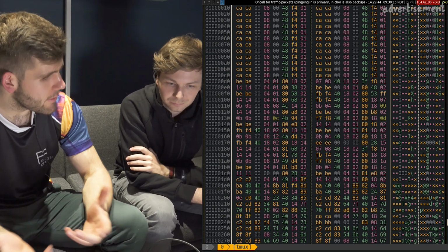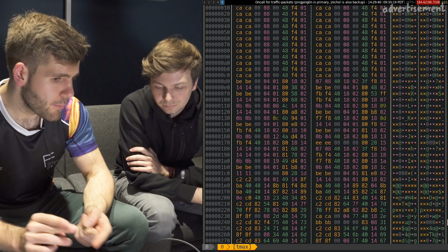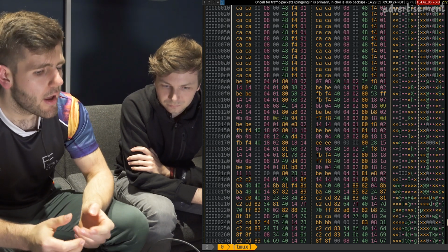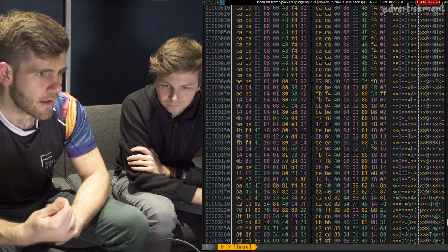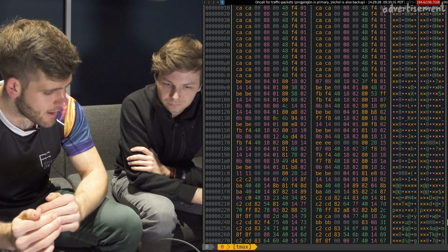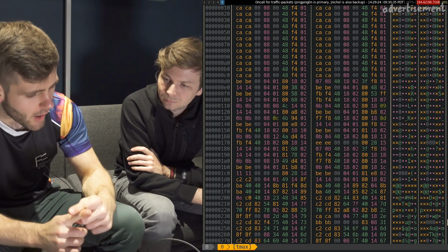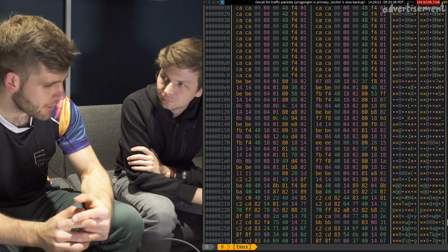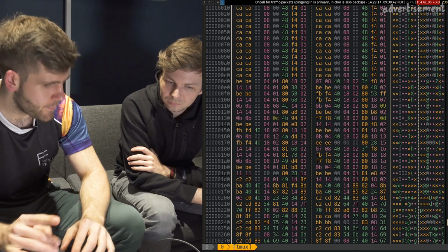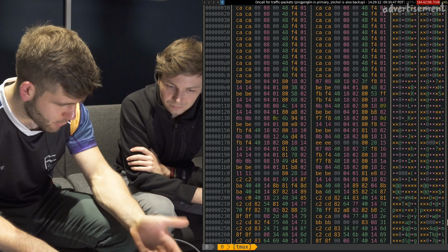But it should, in theory, be very similar to commercial FPGAs as well, in that we are programming a bunch of lookup tables, which is encoded in this logic, and then we are specifying wiring. While a typical FPGA has, at each crossing of wires, a programming bit associated with it, that doesn't really make sense here, so instead we have addressing. And I'll show you how that works when we have a look at the shader. But it's basically the same pattern all the way down